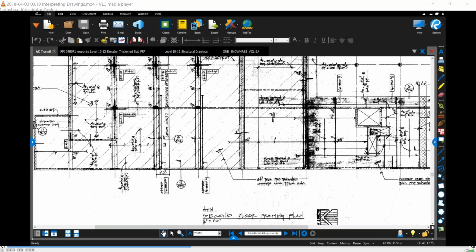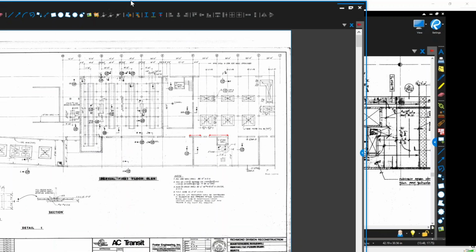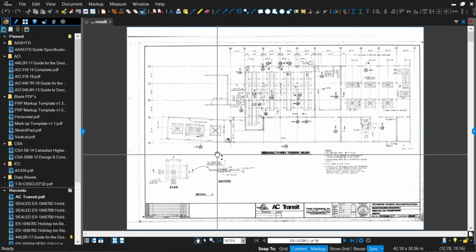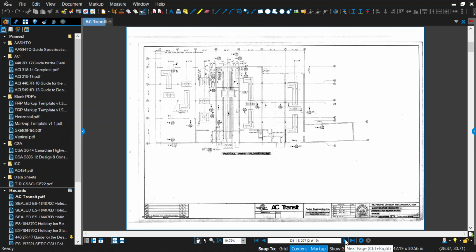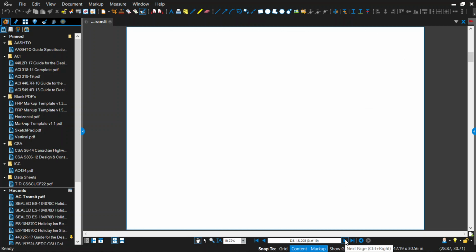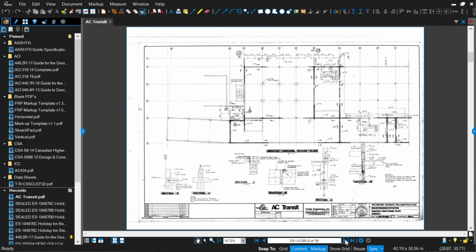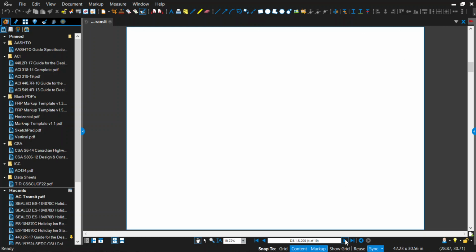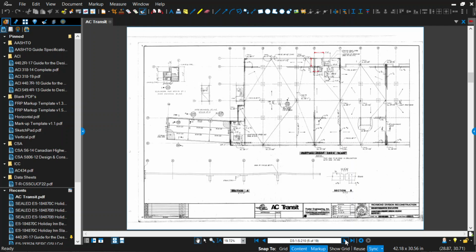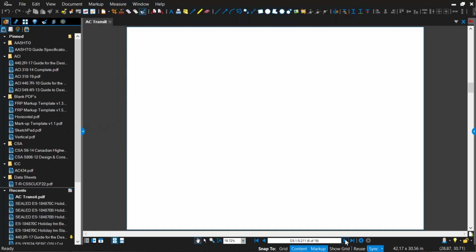So what this is showing you in the slab is where the tendon is. So here it's 1 inch from the bottom, so you're measuring up. And here it's 7 1/4 inches from the bottom. So your tendon profile is gonna look like this. And usually does it end around the middle at the end?